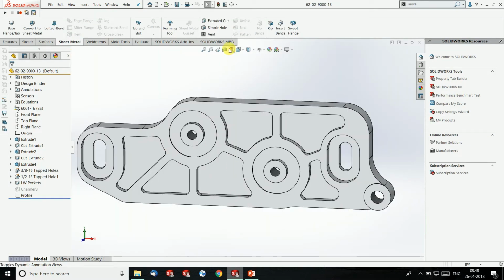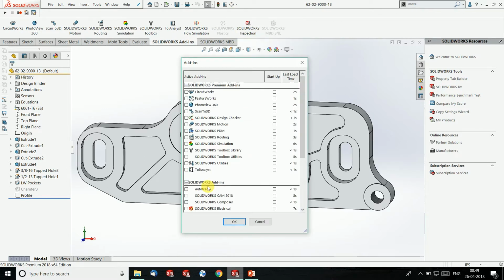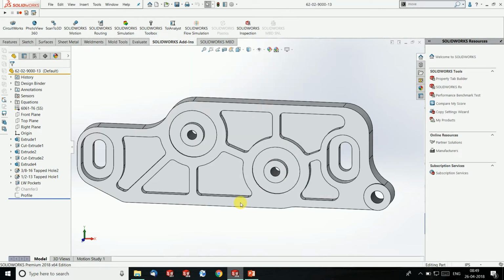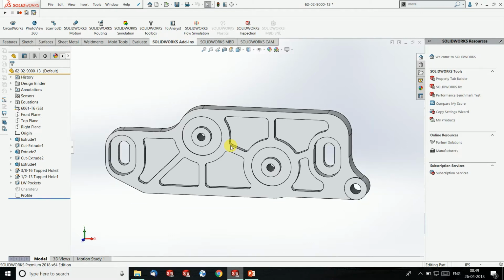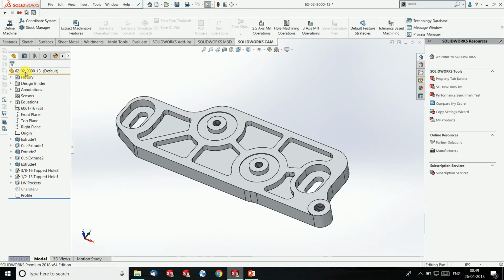Yes, so in the display you can see one of the machining components that is available. What I want to do is create the NC program for the machining operation for this specific part. Alright, so once I have done the model, the one unique advantage in SolidWorks CAM is the automatic feature recognition. So once you have done the model, you can recognize the machinable features automatically through SolidWorks CAM without doing it manually, right?